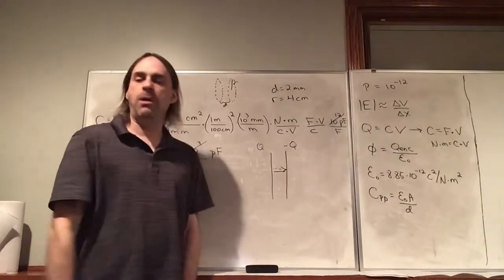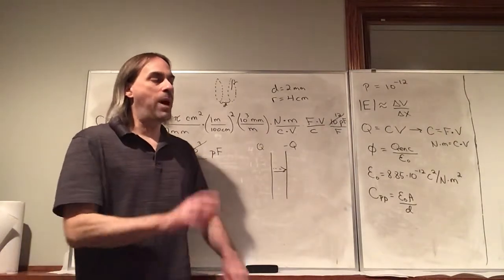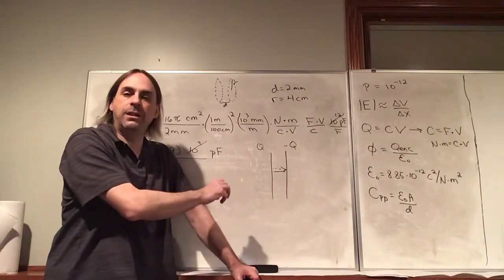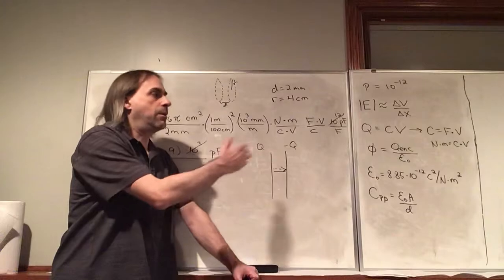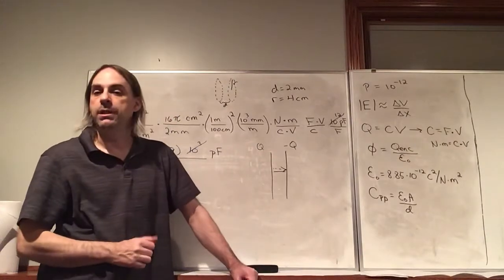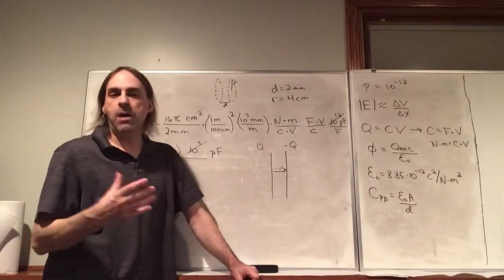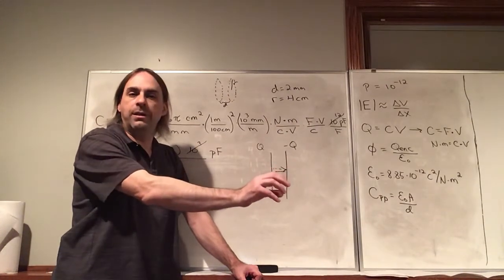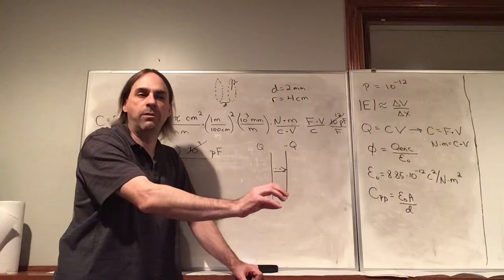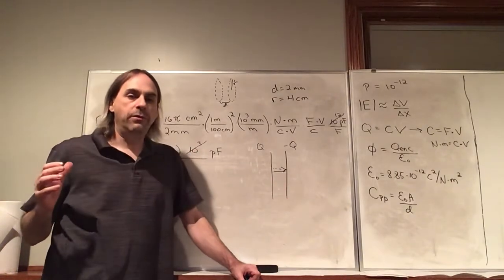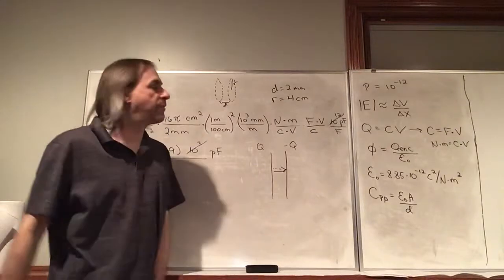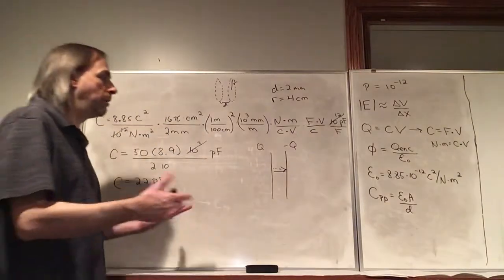And that could actually be a problem sometimes, because turning that dial affects the capacitance to allow a particular frequency to get through. And the problem is that you're a conductor. So if you go over there and you adjust it and get the sound just right, you tune into the right frequency, when you leave, that affects the capacitance, and so that can change the frequency away from what you actually set it to.